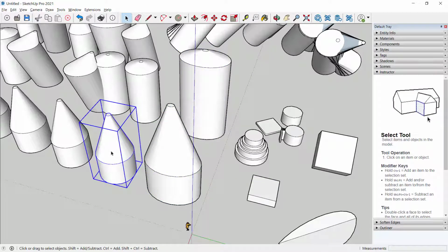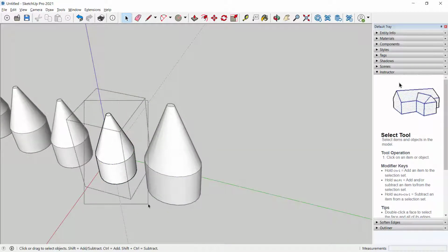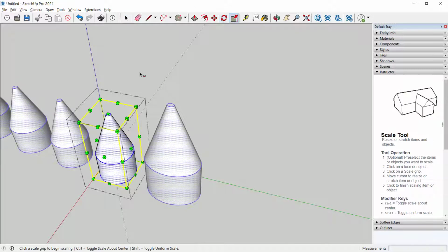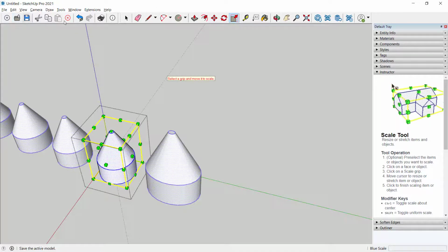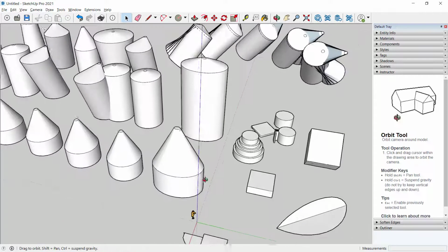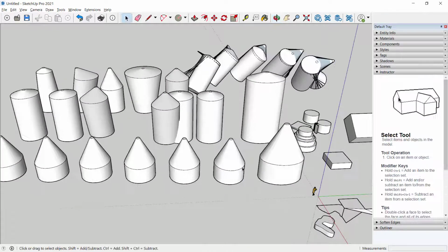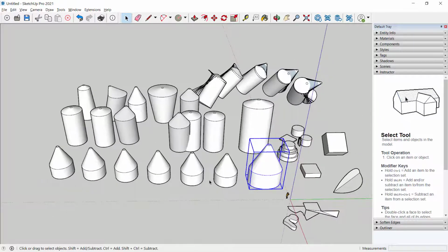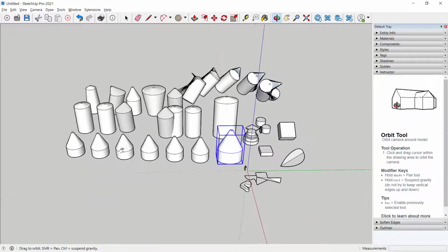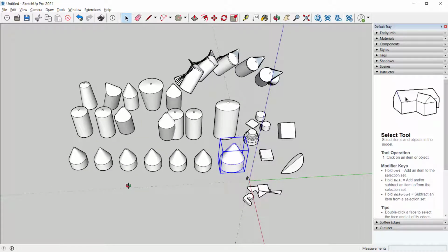However, if I want to scale all the components, I have to edit the component and now use the Scale command. And you see how it will modify each other component. However, it will modify this one based on the proportions of the modified component. So you can actually get yourself into a little bit of trouble, especially if you're dealing with repeated architectural elements like columns. Just make sure that you know what you're doing when it comes to creating those.